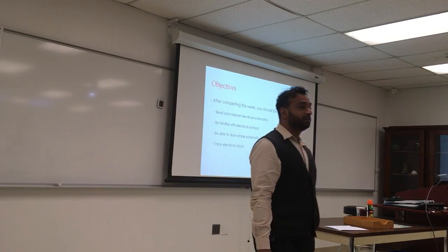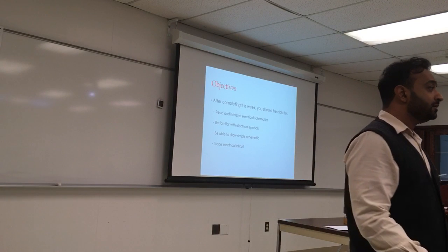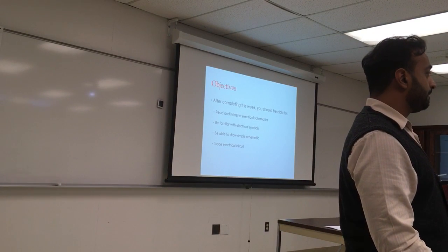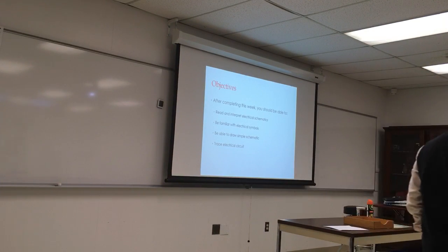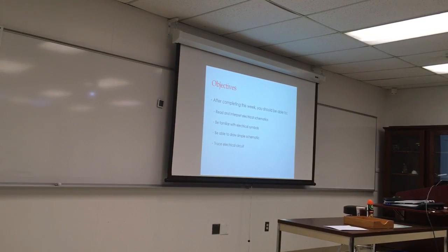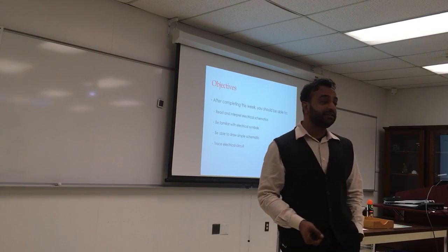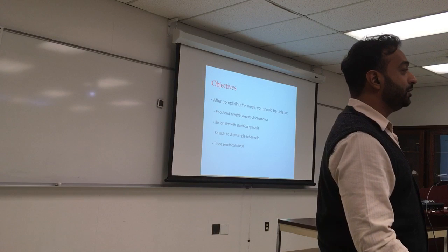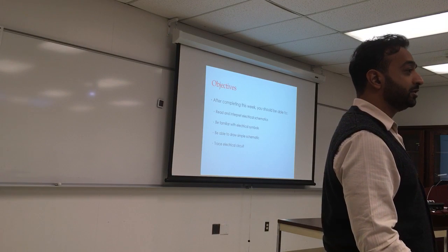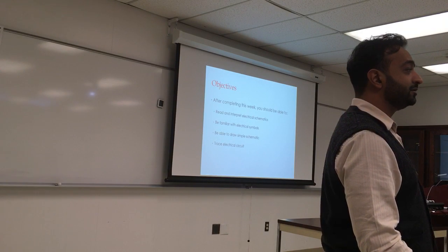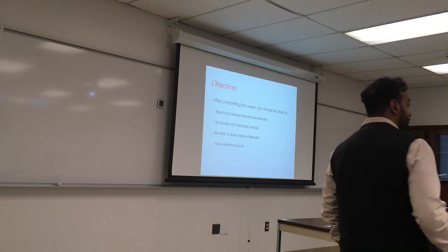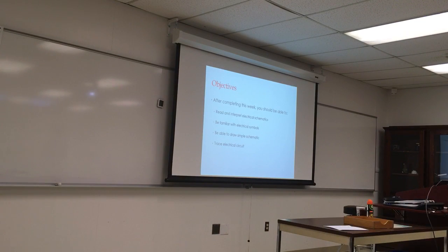Trace electrical circuit. What do you mean by tracing? Like power flow? Yeah. So we do the power flow from the source, till the load, and back either to the ground or to the neutral. If you do DC current, usually there is no return line, there's no neutral. What do you use? Ground. So that's why in the car, you can put it only to one output and use the car body as a ground, and you have enough flow.